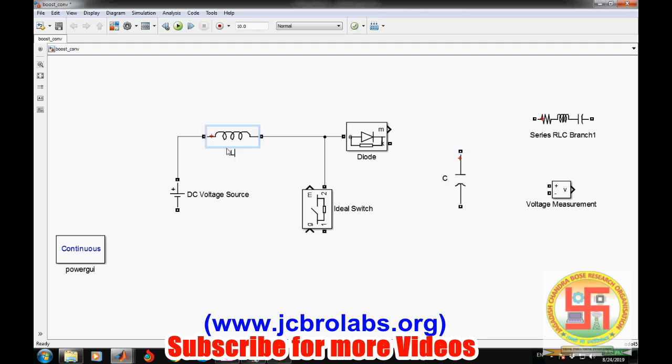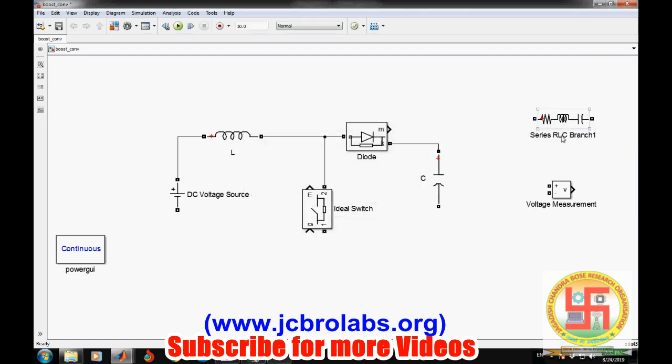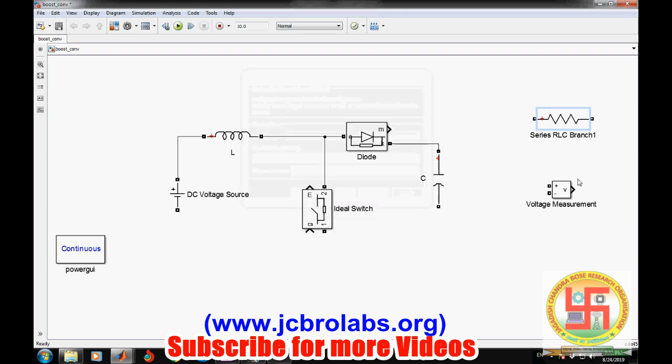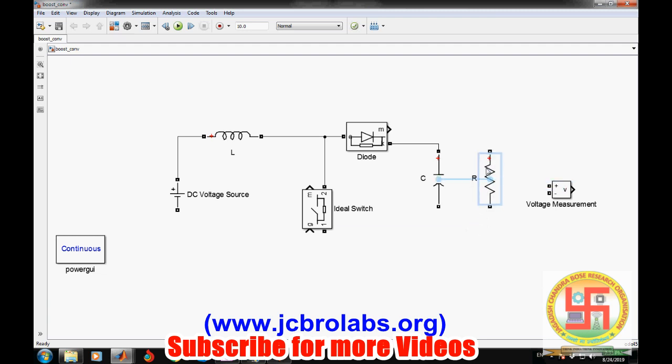Then connect this diode here, and then it has to be connected to the R. We have a specific requirement for the load resistance of 50 ohm, so we'll set 50 ohm. It has not been set, only R. Change it to R, and let's rotate it in the clockwise direction. Now it's done, and it has to be connected here. One point should go here and here.